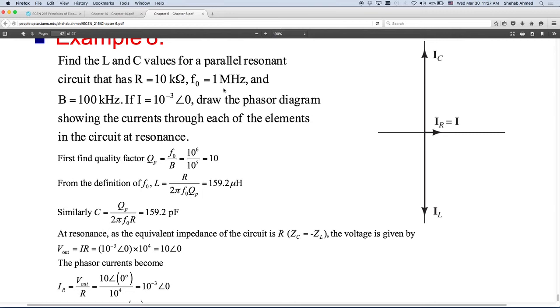And you would like to take that into a computer. Computers read voltages, right? So after the signal passes through your resonant circuit or bandpass filter, you want to measure it and make sure it's a certain value. You will take that current multiplied by a certain resistance. You know this current will not exceed a certain value because your sensor's capability is known, so you would probably choose a resistor to match your computer's maximum voltage input. So typically you will also know the resistance, so you will know your load.